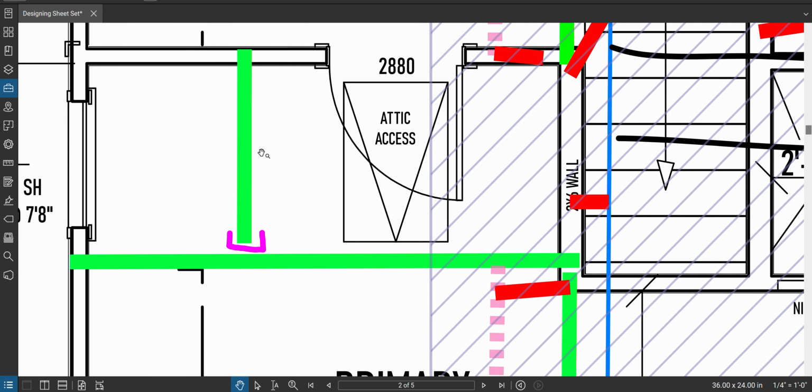And I'm on a wall with blocking. I'm good. And the other one is a, not the bottom, it is a face mount hanger. It doesn't really matter which one super badly. Face mount hanger on a beam, because there's another beam holding it up. And that beam, I don't know what it's going to be made of yet, but I'm going to assume it's commodity lumber because it's not doing a lot of work. So I'm going to go back and say it is a southern pine beam. And that's it.